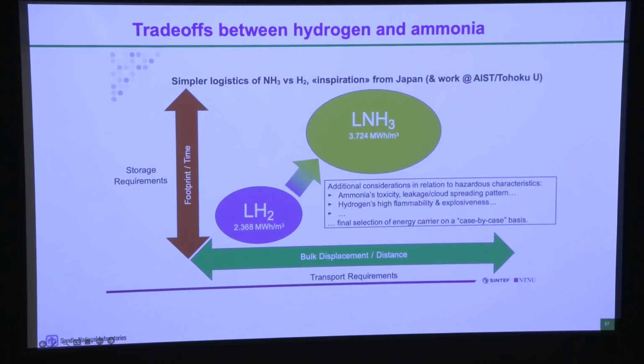the synthesis and conversion of hydrogen processes are only the beginning and end of a longer and more energy-intensive process for being able to successfully use hydrogen as a store for renewable energy. So in order to actually use it and transport it by either ship, train, or truck in its pure form, as I mentioned already, it has to be either liquefied or compressed, and that requires enormous cooling or very, very high pressures.